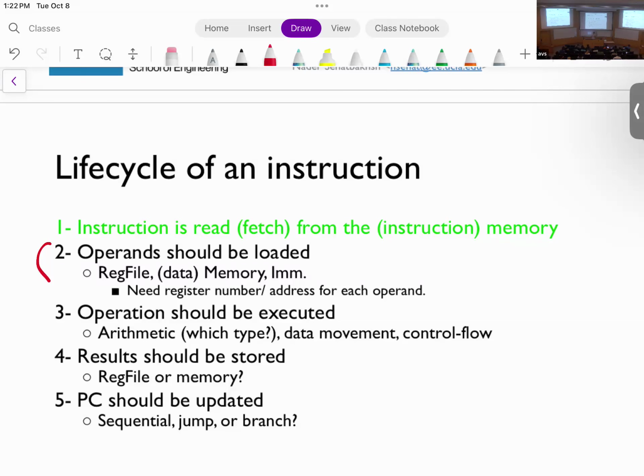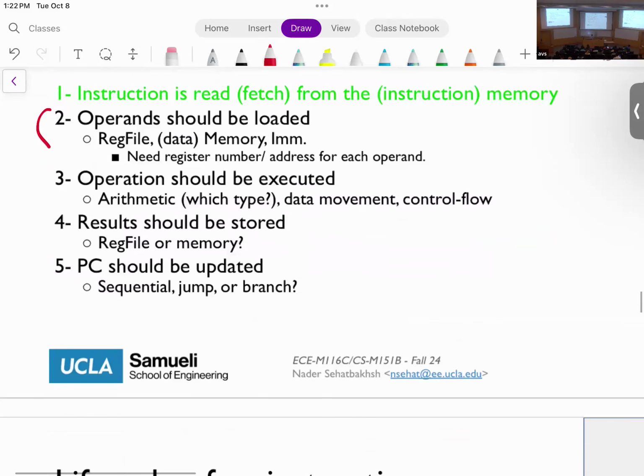The controller basically understands the instruction and provides control signals to us. We designed this using an FSM. An FSM has multiple different states. In our current design, we traverse all the states in one cycle. So we do everything required for one instruction in just one cycle, and we call this single cycle design. Okay? So let's continue. We are here. We need to do this one, and this one.